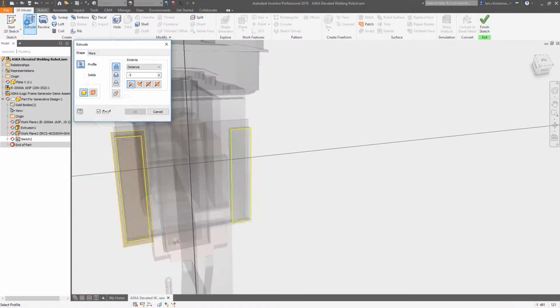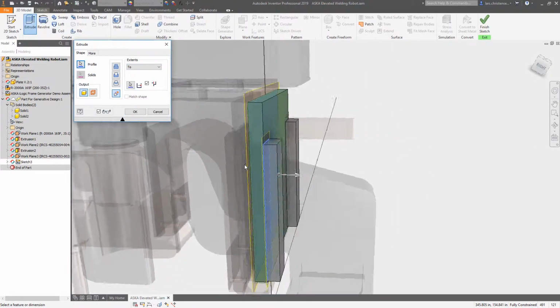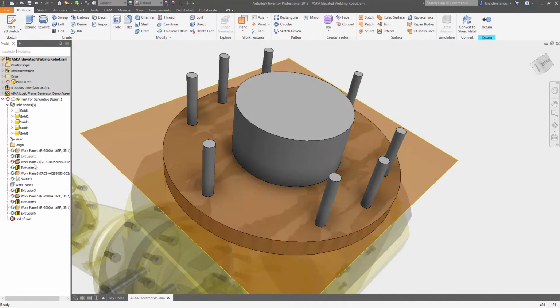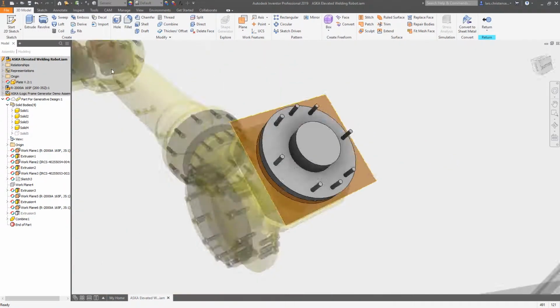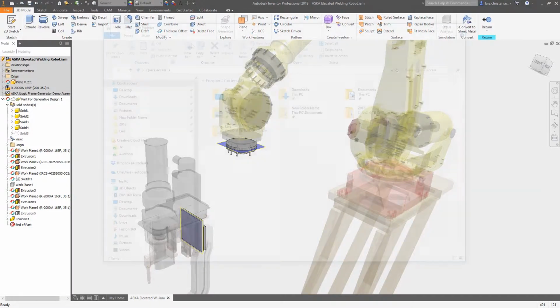Obstacle regions are the defined area where we don't allow the material to be built by Generative Design. This includes space for screws, counterbores, and any tooling that needs access. The modeling within Inventor is done with three simple commands: sketch, project, and extrude.